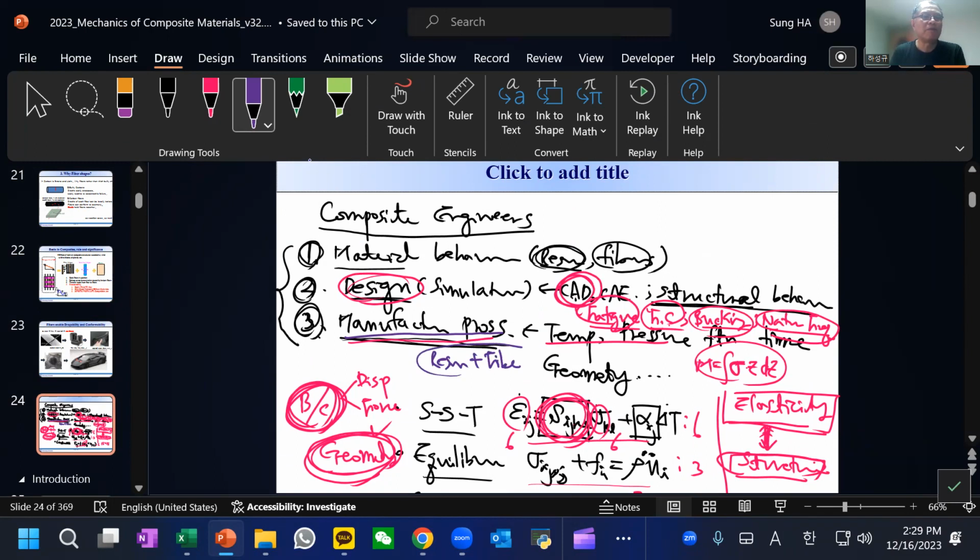How can we impregnate fiber into the resin system by proper temperature or proper pressure, and that is the concept of manufacturing procedures. We went through infusions, but the other procedures will be the same, either RTM or filament winding. All that matters is how to impregnate fiber into a resin system.